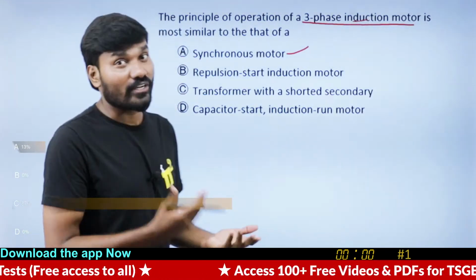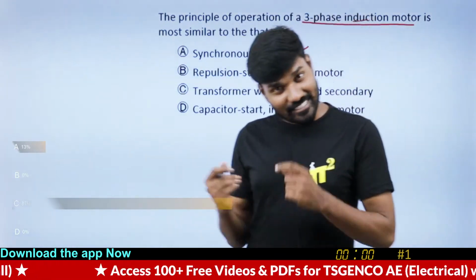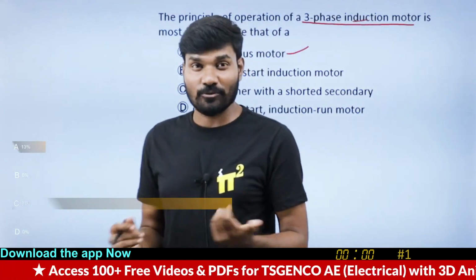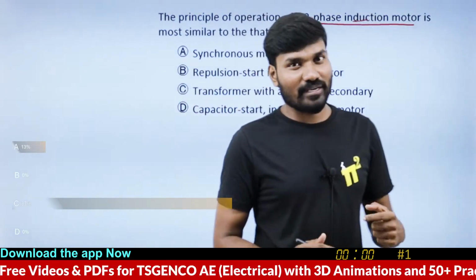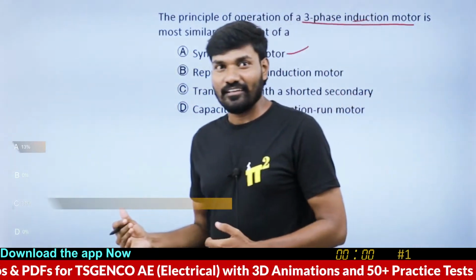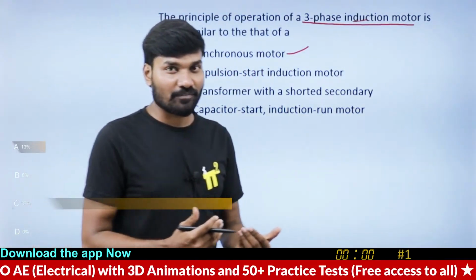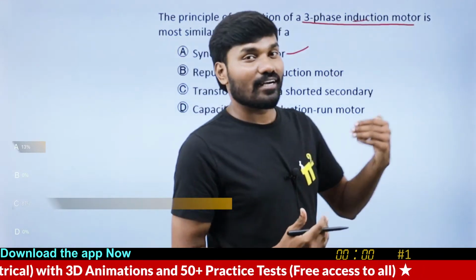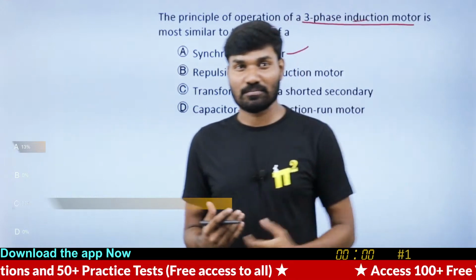Maybe less, maybe more. Yes, you can still call it a motor. You normally know that if the speed of the rotor is greater than synchronous speed, it will work as a generator. That's a regular induction machine, but there are some special induction motors. You can still operate the induction machine as a motor even beyond synchronous speeds.